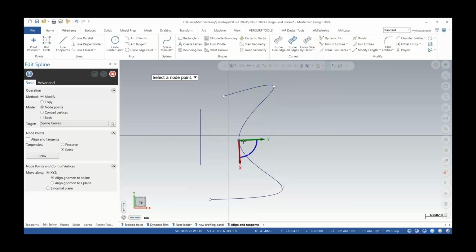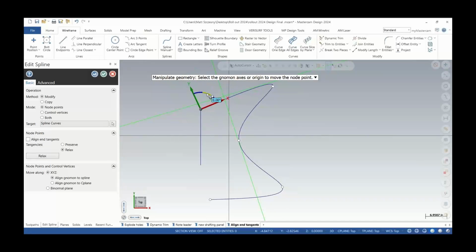And you get these points associated with where those splines are created. And what I can do is select an endpoint and use this almost dynamic transform option here to better modify that spline itself. Now this is the old method of manipulating the spline. I'd have to try to find tangency or manipulate it with more manual work.